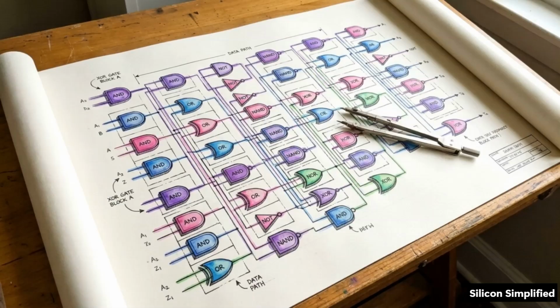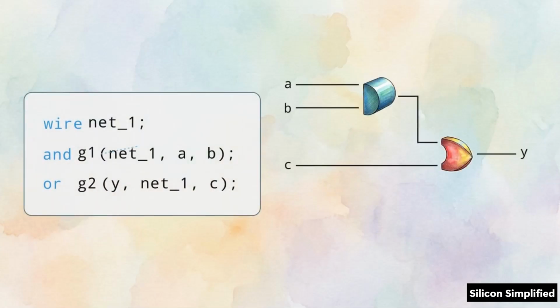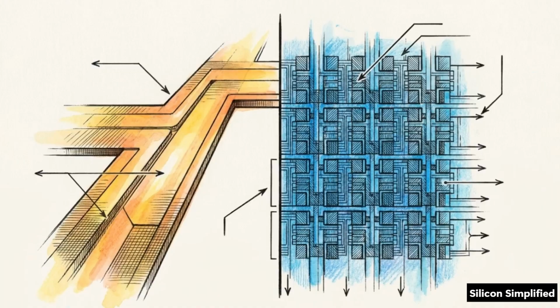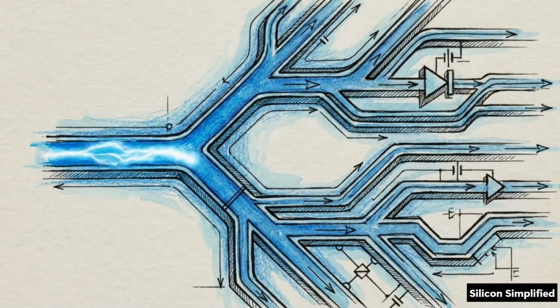It serves as a functional blueprint for chip architecture, providing a text-based syntax that maps directly to the physical layout and timing of electrical signals. Because hardware either lets electricity flow freely through logic gates or traps it inside memory cells, Verilog splits itself into two distinct worlds. Each physical state is controlled by its own specific set of rules. The very first world is combinational logic.